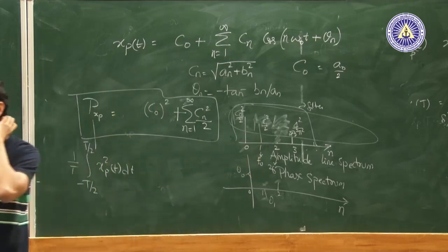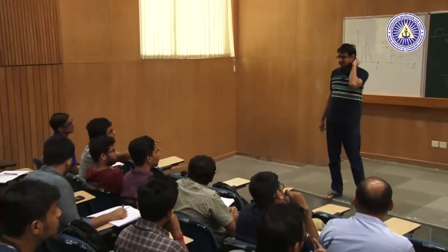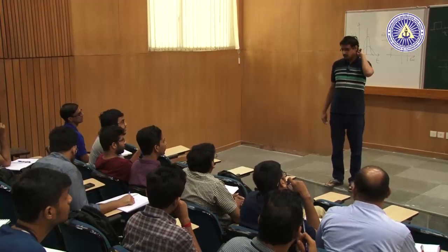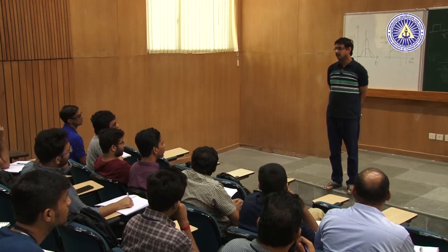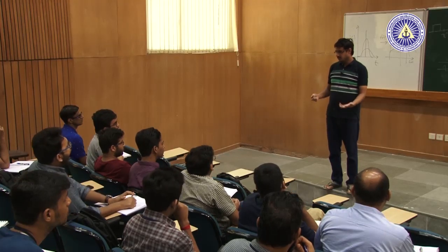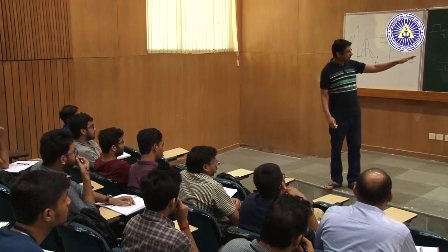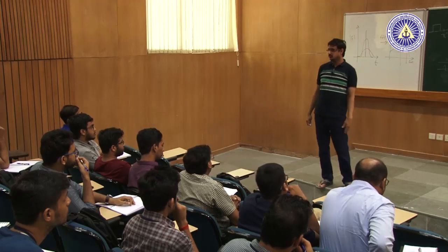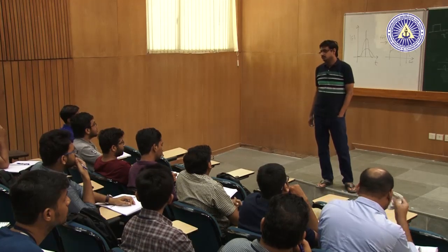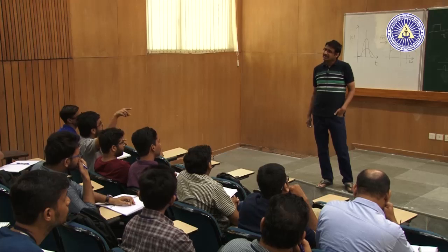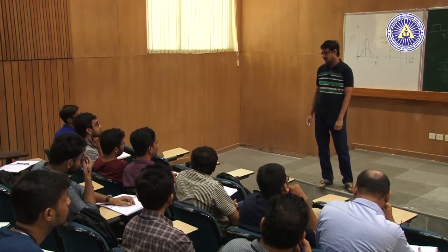Sir, you said that usually after C7 or C8 the values decrease for this wave. Is this usually seen, that when n increases the Cn value decreases? Usually it decreases for any physically realizable function. If you have any physically realizable signal, then the amplitudes usually decay as the higher frequency terms go out, and the other way around usually does not happen. C0, C1 small and Cn large happens, but only in a very special type of signal, which many times is not realizable.